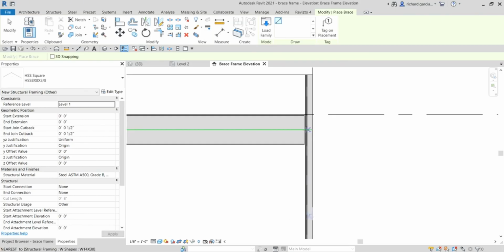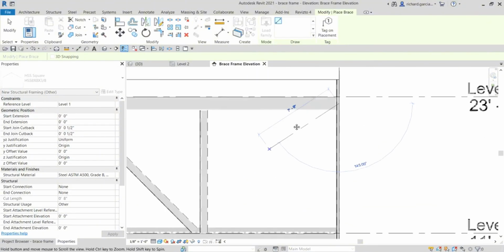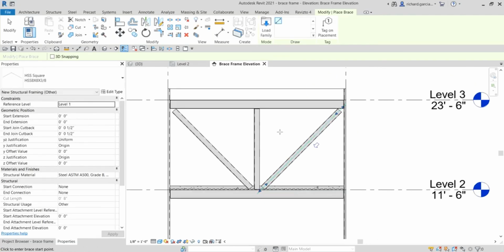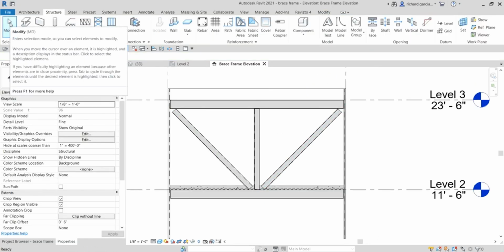The green line disappears. Now, what I'm going to do is hover my pointer somewhere here, and then type SE, so it will snap to the endpoint of that analytical line. Once you see it, it snaps. So you click that, and after that, you may now click the midpoint here. And there you go. Okay, so that's the example of the brace. That's how you create the brace.